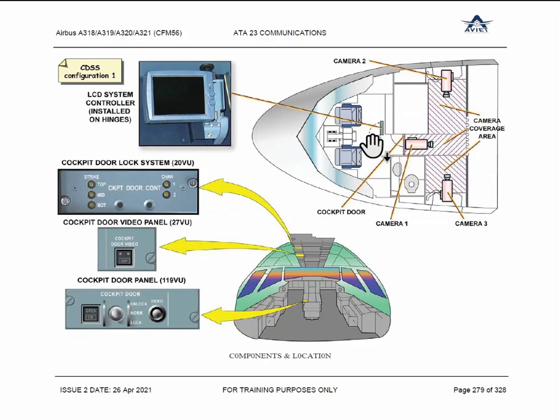Correct, inside the cockpit. And this strike is also available for extra protection on the door. So magnetic strikes are available at 3 places: top, mid, and bottom. So the cockpit door is very, very strengthened nowadays, and the cockpit door surveillance is also very strong. It is the sole discretion of the pilot to allow someone inside or not, even cabin crew. Even the cockpit door is also monitored by the number lock.